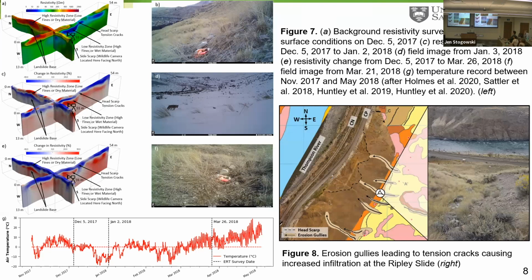So the permanent layout of electrical resistivity tomography was installed as a part of a collaborative effort with both the BGS and the GSC. Visual plots such as these were reproduced on a weekly basis from the BGS between 2017 and 2019. Increasing water content or negative changes in resistivity are depicted in blue on the following plots. The wildlife cameras also show surface conditions and accumulated snow present at the time of each ERT measurement, while air temperature for the survey period is plotted across the bottom.